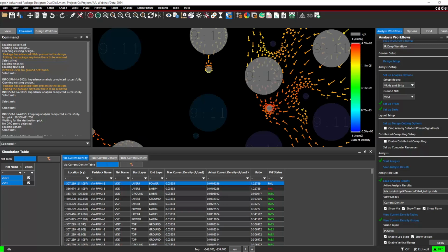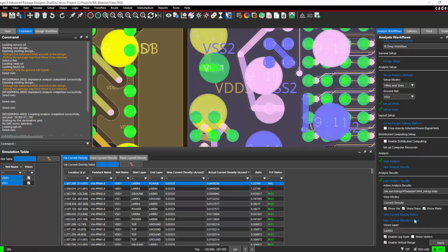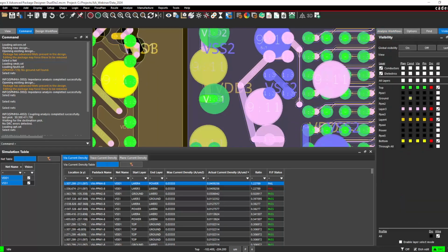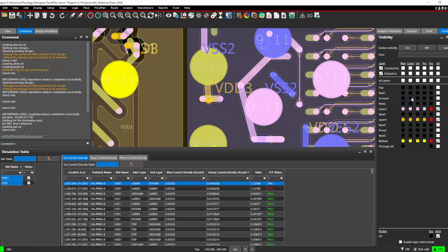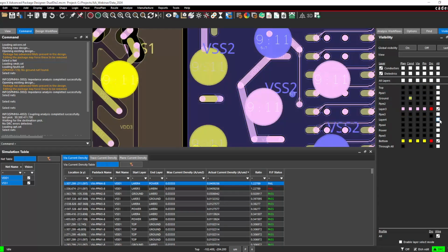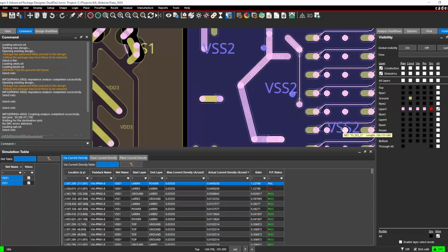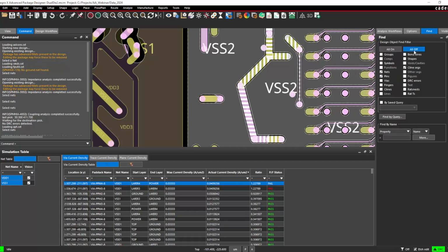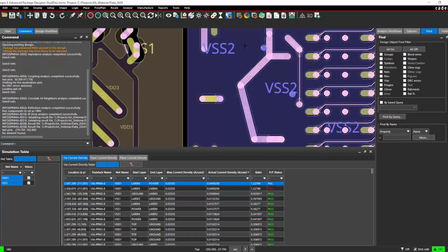So we found two different problems, which will likely take two different solutions. Let's first solve the IR drop issue by widening the routes, the connect lines that are in view currently. Change the visibility settings to make this easier to access, and then we'll just do an area select to change the widths. Oops, I selected a little bit much here. Let me undo that. Need to change our selection here. Deselect.